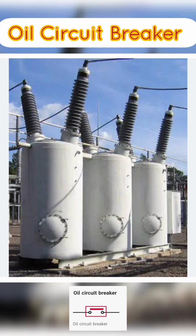An oil circuit breaker, OCB, is a type of electrical switchgear used to protect and control electrical power systems. It is commonly used in high-voltage substations, where it functions as a part of the protection system for electrical transformers and other important equipment. The OCB operates by using oil as an insulating and arc-quenching medium. When a fault occurs in the power system, the OCB interrupts the electrical current by creating a high-impedance arc path between two contacts. This arc is then extinguished by the oil, which cools and absorbs the heat generated by the arc. The OCB also has mechanisms to control the arc and ensure that it is extinguished quickly and safely.